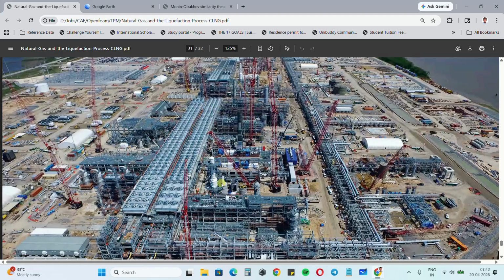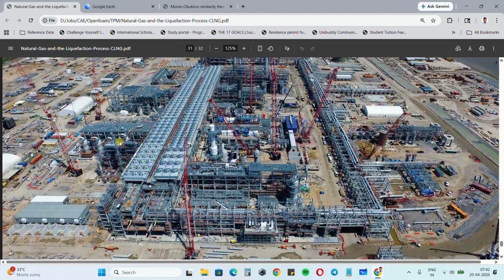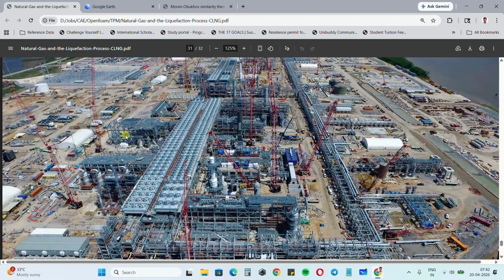So the goal of the simulation is to evaluate, for a proposed plant layout subject to the environmental conditions or the atmospheric boundary layer flow, how this hot air is getting dispersed into the surroundings, and we want to probe the inlet temperature accordingly. That's the objective of the study.